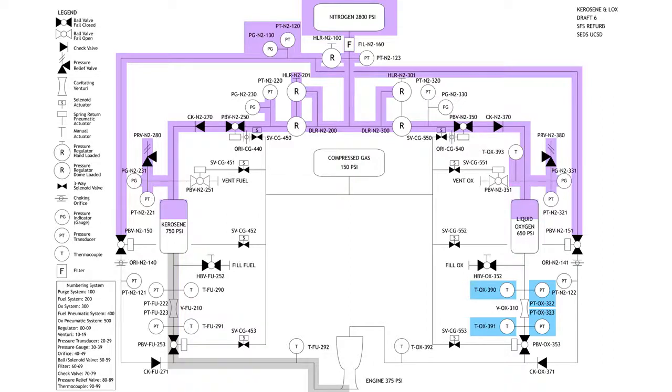From your cavitating flow equations, you don't need a flow meter. The Venturi itself, a cavitating Venturi, acts as a flow meter. If I have pressure and temperature of my fluid before and after, I can get flow rate. So it comes from the equations. You don't need P, V, and T. You only need P and T, basically. That's what it comes down to.